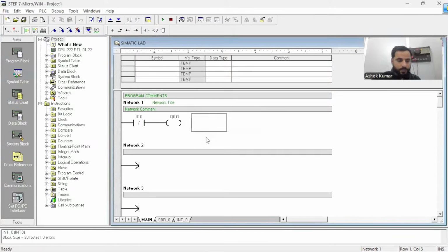I told you, once you understand the concept of Allen Bradley, it will be very easy to understand Siemens as well. Whether you are working on 1200 TIA Portal or anything else, it's very easy for you now. Now it is automatically detecting the communication, but in any case, we may face errors while downloading for the communication. It's not communicating because of the cable or port numbers.